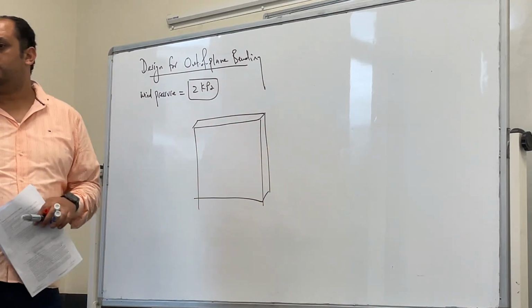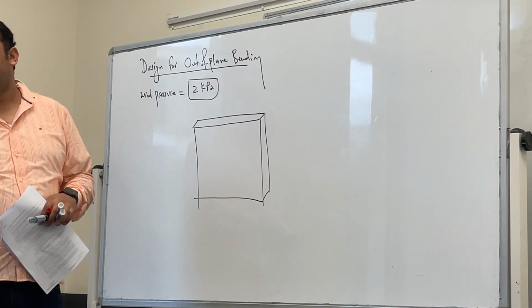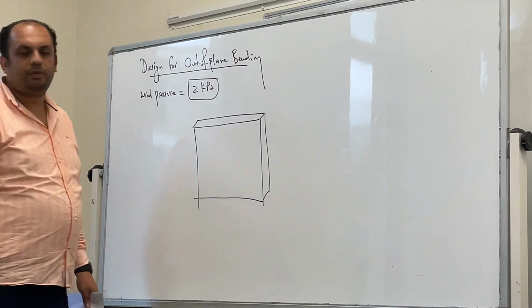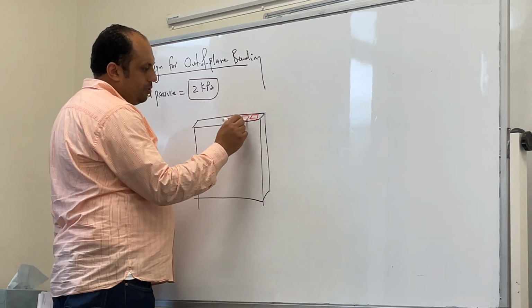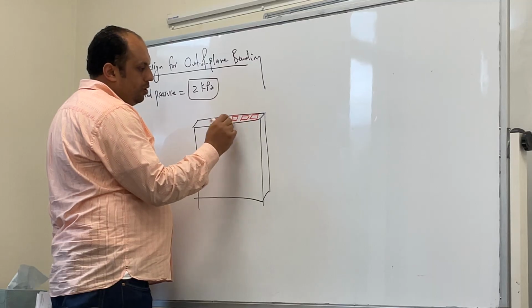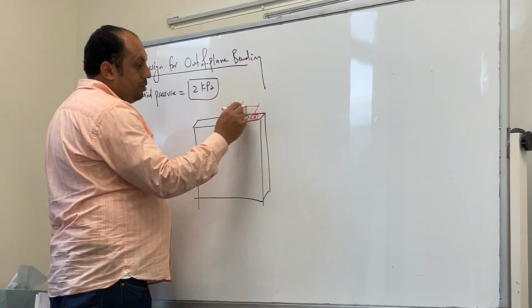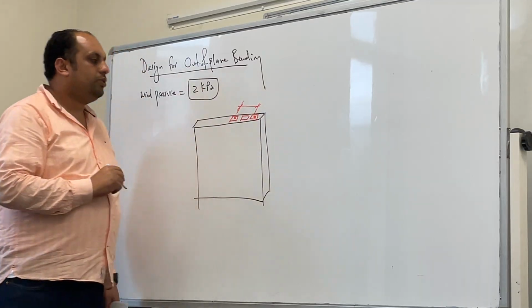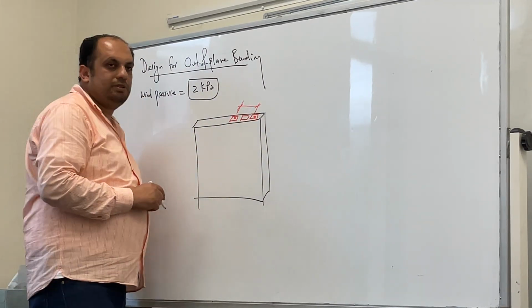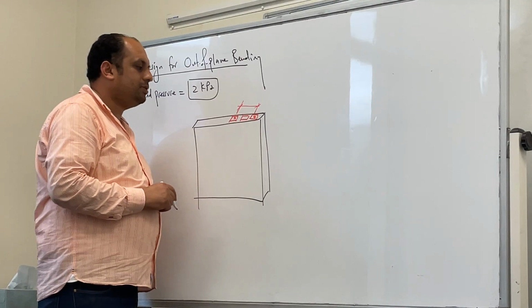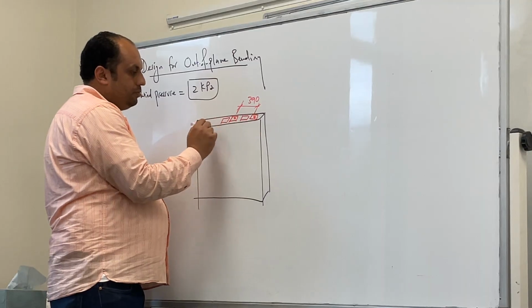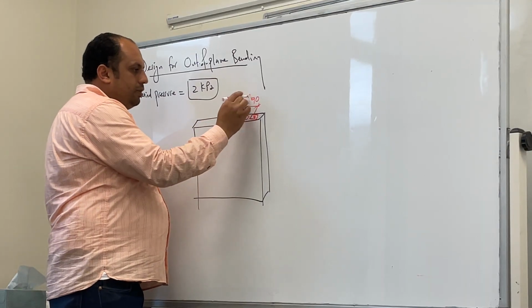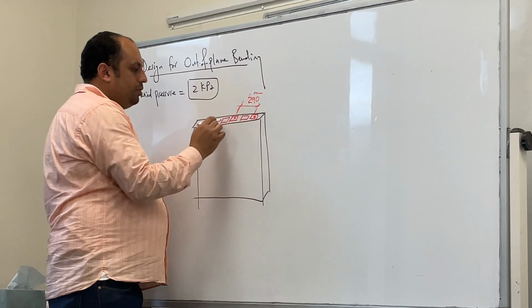I don't think 200 works. I think 300 works best, though. I realised that later, because you have to make the spacing fit into the block, because you've got the 10 meter joint as well. So we can give it a range. So now, what is the max distance between the bars? 390? 290. Sorry, I took 290. I took 250. I think 300 works the best.